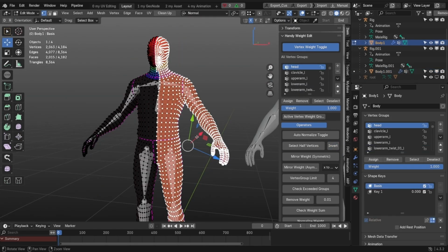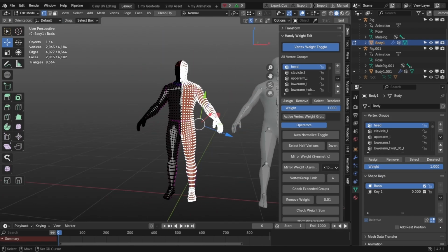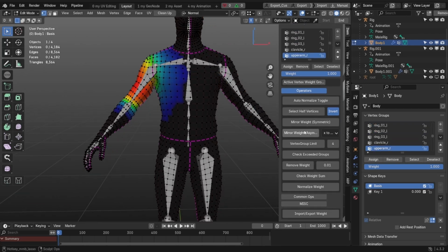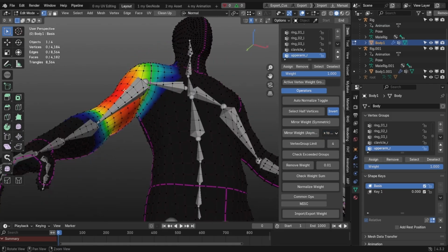If not, there is option 2. Although mesh is not perfectly symmetric, it is symmetric proportion-wise. Select mirror direction, choose active bone or all bones and mirror weight. This method uses closest proxy, so for areas that are close to each other, some manual fix may be required.